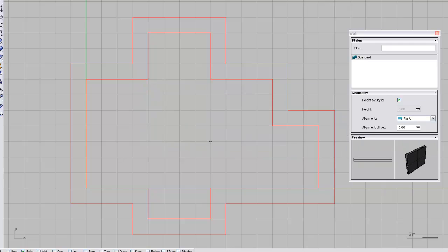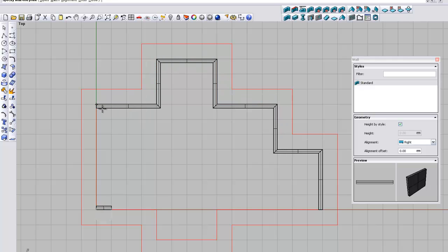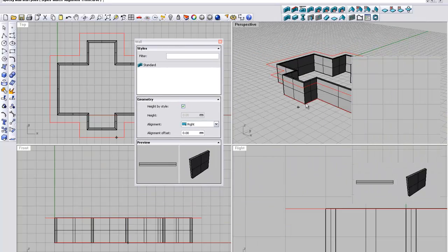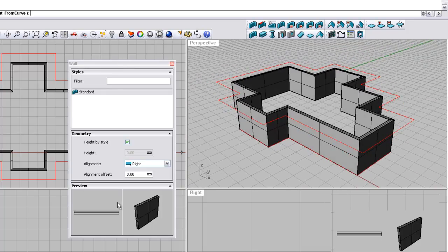So what we're doing in this case is just making a standard wall length, just tracking along a little construction line that we've made. Now we could have grabbed the entire boundary and then done the wall all in one go, but in this case I've just done it piecemeal. It connects the wall up as a continuous unit, so we've automatically got a 2.7 metre high, 200 thick wall.